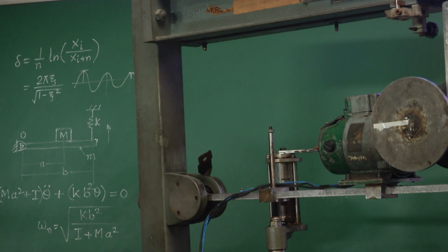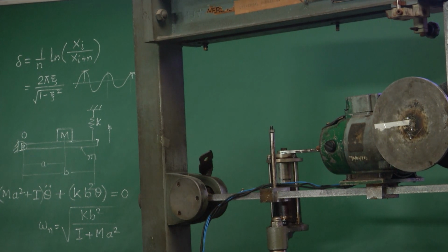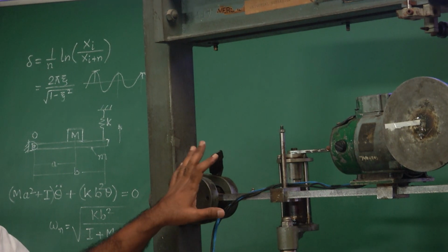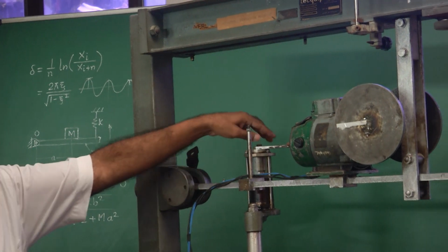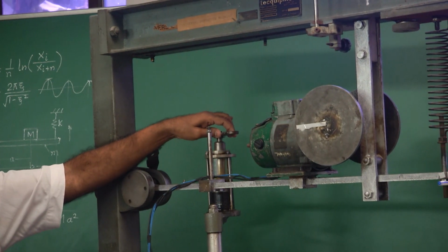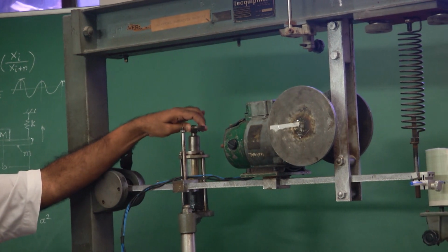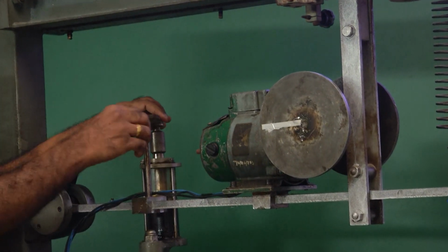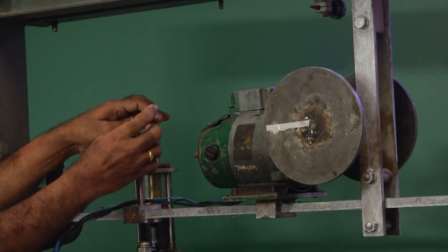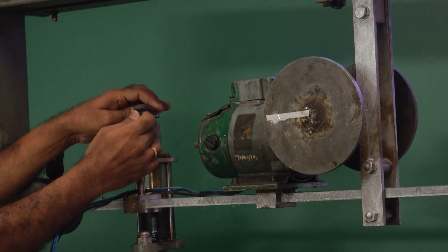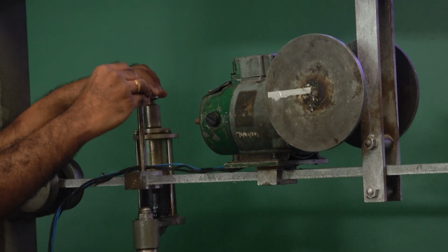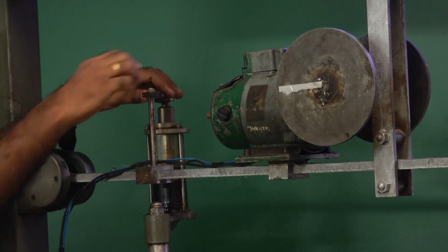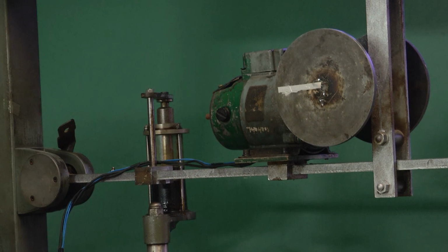in the system. Now, having seen this sort of an undamped case, although there is damping, the damping is not coming from a dashpot, but from a variety of other sources as I discussed. We do have a dashpot, a formal dashpot, which is like a cylinder filled with a viscous fluid, and then there is a piston that moves back and forth in this viscous fluid. So, I can bring in this dashpot into the vibratory system. So, apart from the mass and the spring, I now can bring a dashpot connected to it, so that our system truly then becomes a spring mass dashpot system.